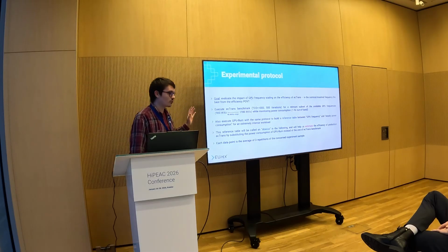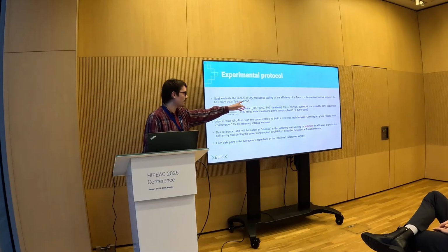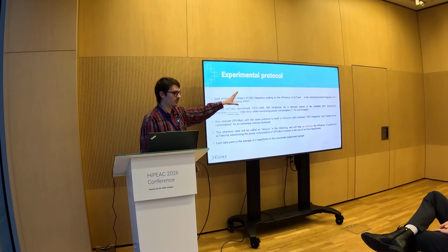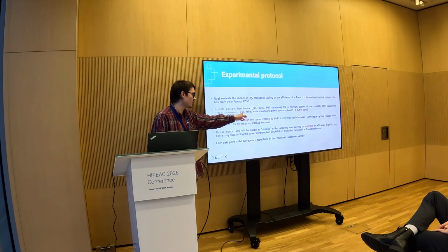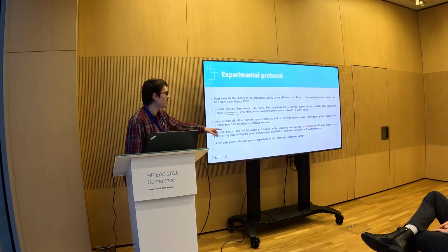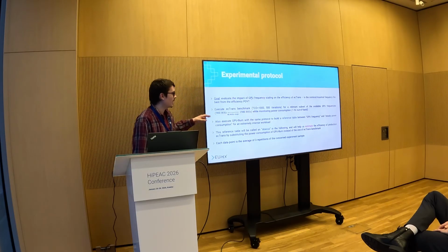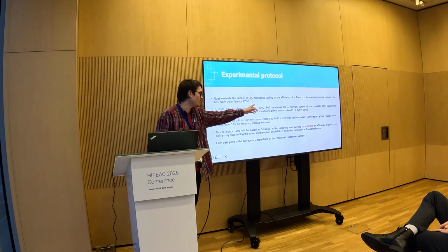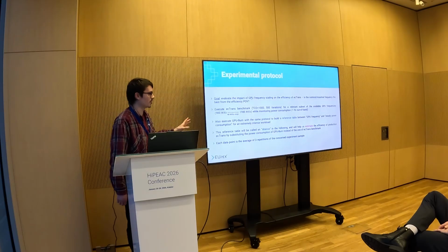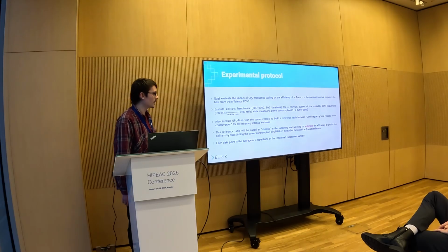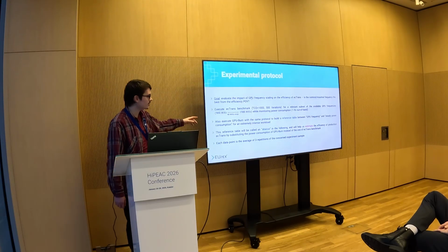Well, that's quite simple. I selected a subset of the GPU frequencies because there's quite a lot, and I didn't want to burn too much GPU hours. So I selected the subset 900 MHz to 1980 MHz. That's the reference or nominal frequency here, with 90 MHz steps. And for a TCU of 1000, I executed EC trans while monitoring the power consumption to see if there was one frequency that was better than the others.